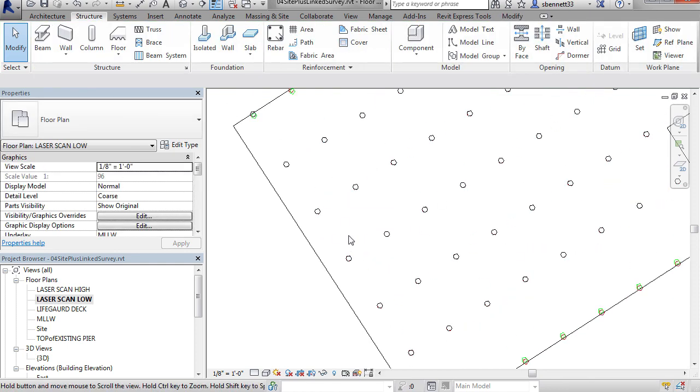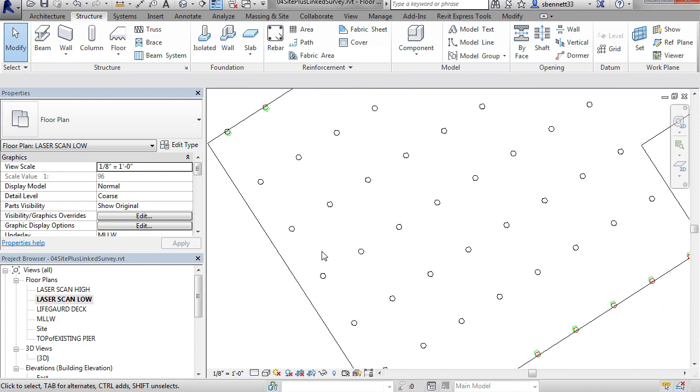The reason that I'm ungrouping them is twofold. One, because it's an existing structure, I don't anticipate needing to flex the array of these objects. Two, we need to be able to attach the top of these columns to the bottom of our wood structure.